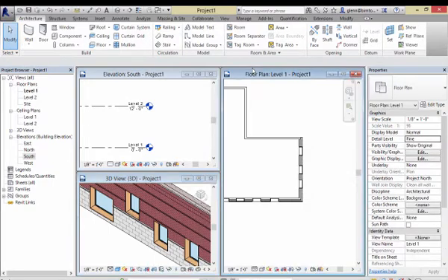So here's the other thing that works as a general principle for these component families, and that is you can load in more from libraries. You can load more in from the Revit library, which is installed on your disk. You can load more in from a lot of user group sites like Revit City, which have huge collections of libraries of pieces that you can load in for custom objects that aren't standardly in the system. You can go to seek.autodesk.com, which is a big collection of manufacturers' parts put out there, kind of like Sweet's catalog. So if a specific manufacturer has a specific component they'd like you to specify in their project, if they put a Revit model out there, you can load that in and drop it into your model.